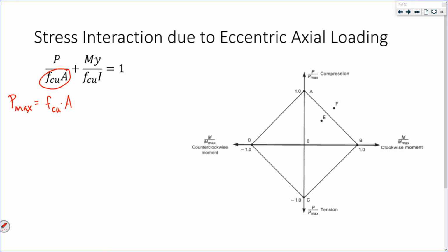If I look at this, right, stress equals, maybe if you do a little off to the side, stress equals M Y over I. If I rearrange that, M equals the stress associated with compressive failure times my moment of inertia over Y, that would be my maximum moment.